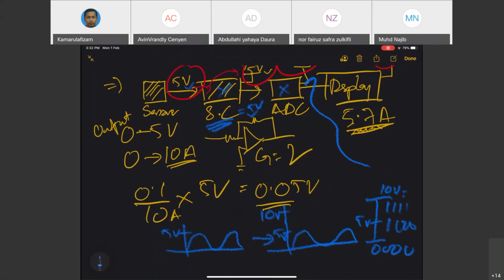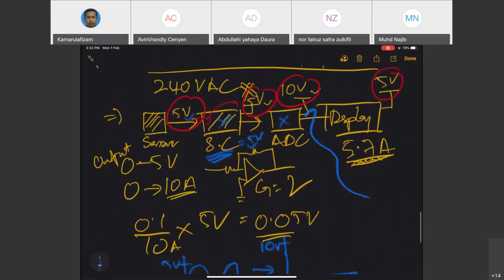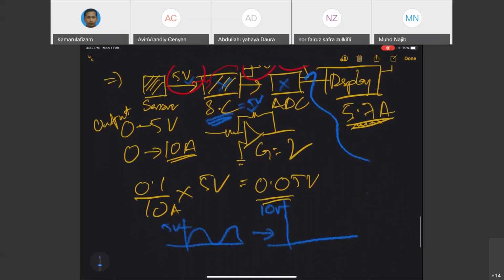All right. So if your information is not being amplified, basically your full scale information is basically just down here. Okay. That's why just now, if the operating voltage basically change, all right, you need to amplify the signal to the operating voltage of the next unit who is going to receive your signal.